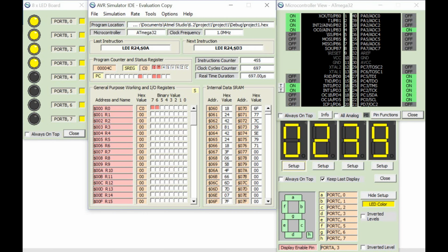Then it moves to task 2. These LEDs will keep displaying this pattern as long as no interrupt is triggered. When INT0 or INT1 is triggered, task 2 will be paused for a while to allow the interrupt, and continues its operation when the interrupt finishes. Let's see what happens if we turn off pin D2. Here, task 4 will be executed as pin D2 receives a falling edge signal and triggers interrupt 0. The parallel LEDs display the night rider pattern. Then the operation continues with task 2.